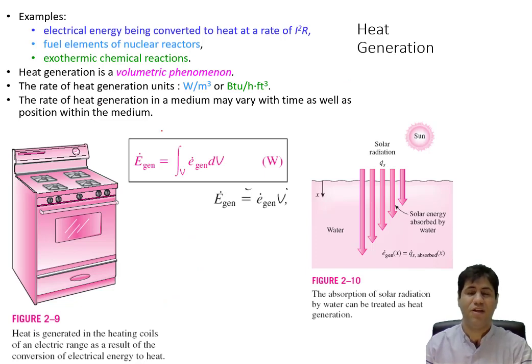by conduction. The other important thing when we are calculating the heat transfer for an object or medium is if the object also itself generates any heat or thermal energy or not. For example, when we have a hot wire, we are going to calculate heat transfer from the inner surface of the wire or from the center of the wire to its surface, for example. Then we have temperature difference between them. We can calculate heat transfer. So heat generation in the medium also is important.